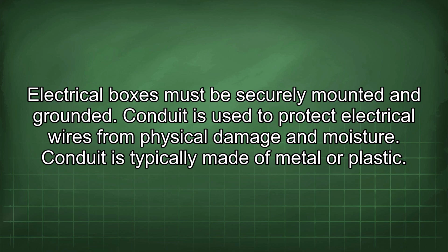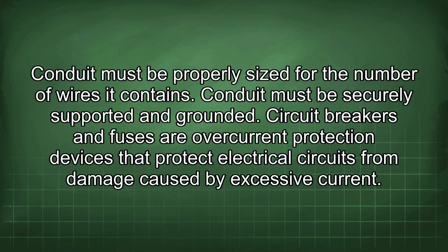Conduit is used to protect electrical wires from physical damage and moisture. Conduit is typically made of metal or plastic. Conduit must be properly sized for the number of wires it contains. Conduit must be securely supported and grounded.